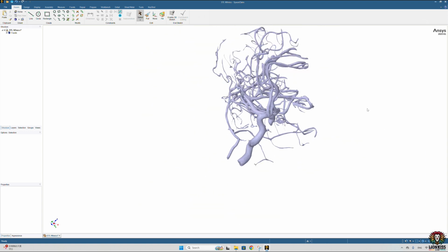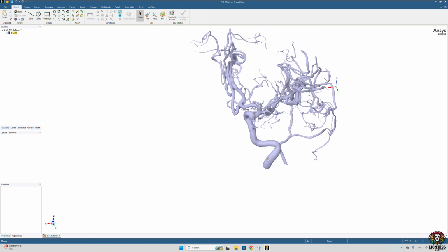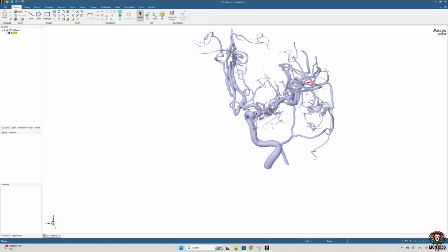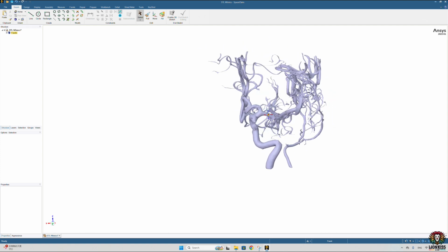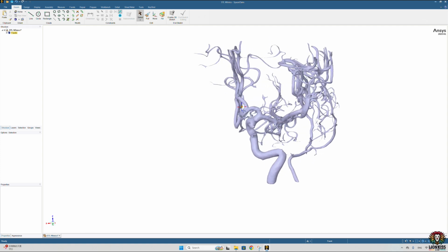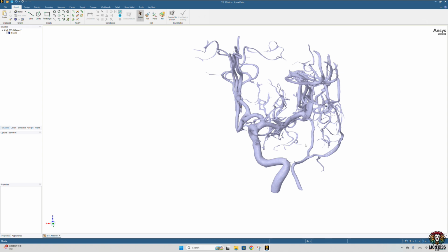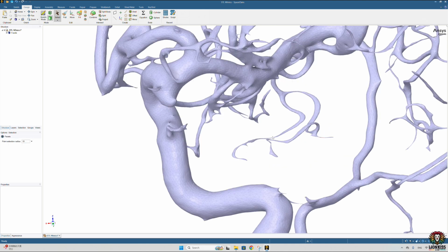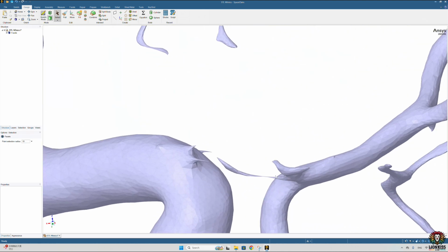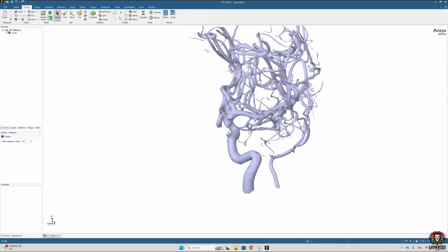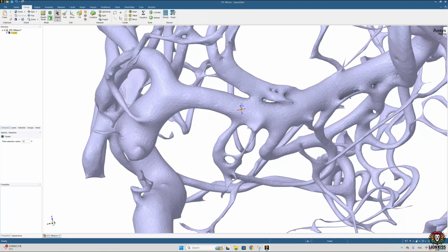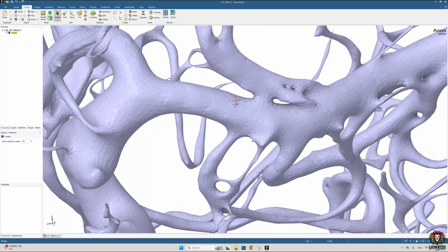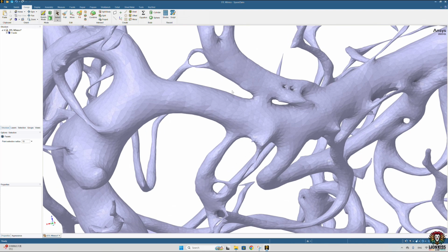And you can see in the different angles, and our main, this artery is our target because we need to simulate this one, but the other parts are extra, these areas are extra parts, so we need to delete them. So for that we need to go to selection, and from the bottom we select the paint, and with paint you can see we will cut it from here because our main target is the aneurysm area, so we will cut from this part. Just right click and delete.